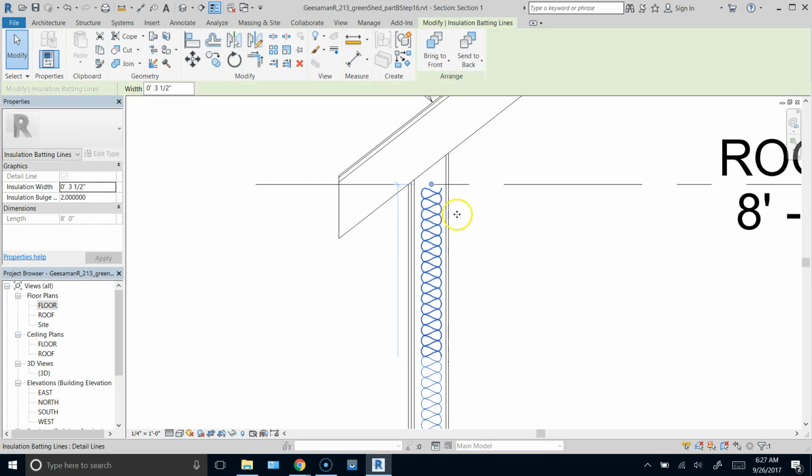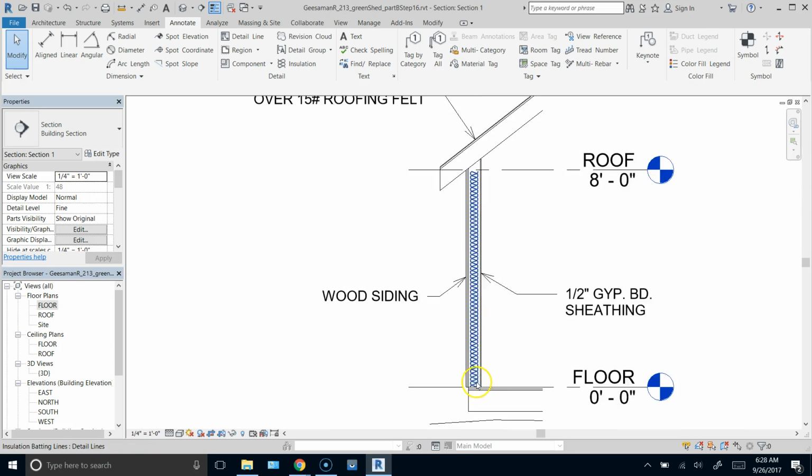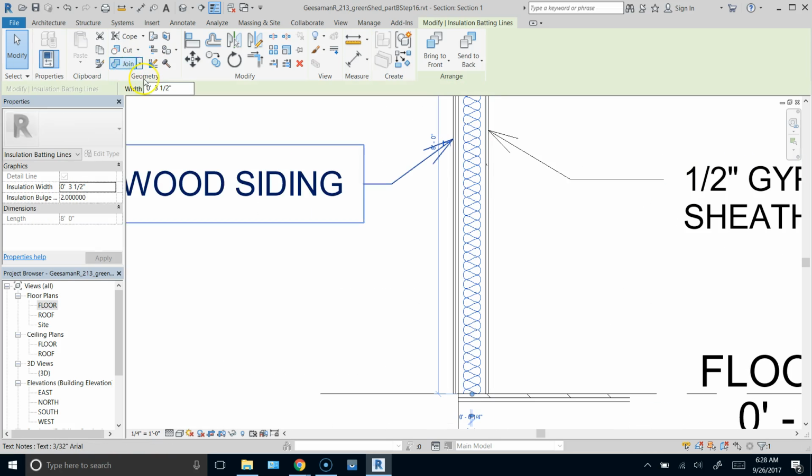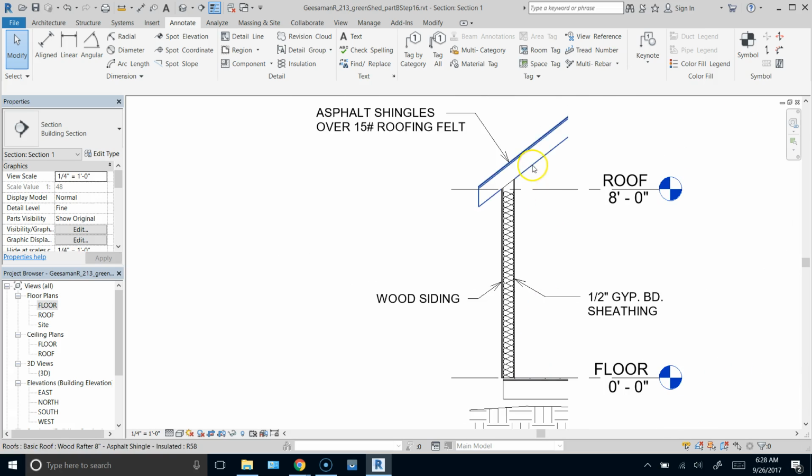One of the things that may have happened is our insulation may have moved from the center, so I'll drag it out temporarily and drop it down the center line. That's the center line, so I saw that blue hash line. Now that we have 5.5 inch stud width, let's make our insulation 5.5 inches. And now it fills up the whole stud cavity, exactly what we wanted.